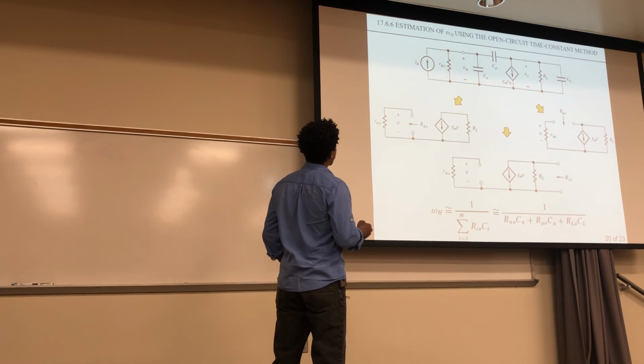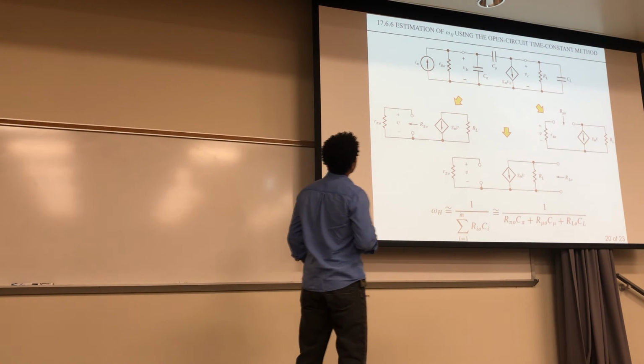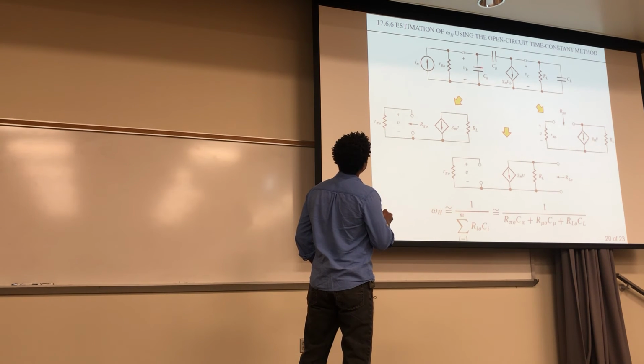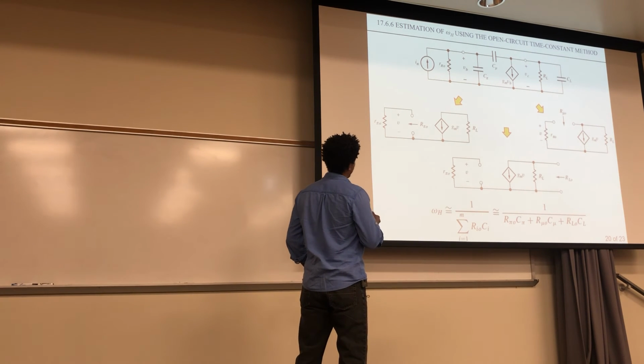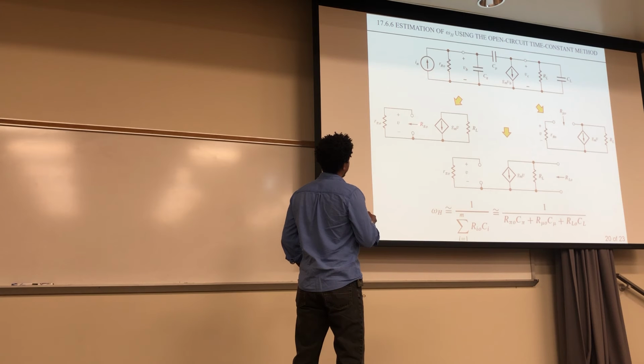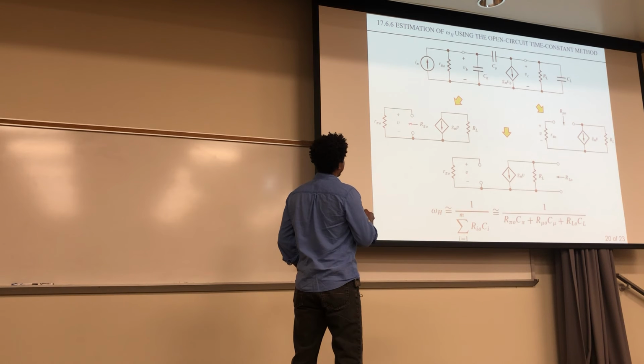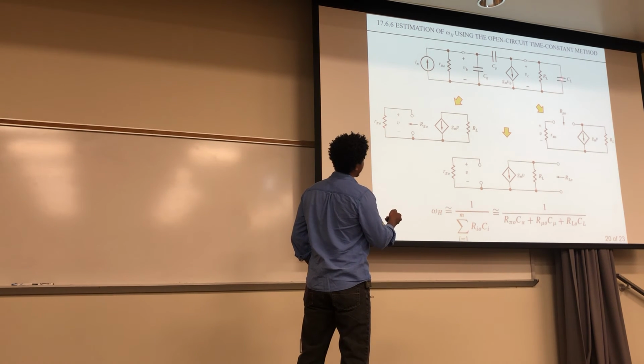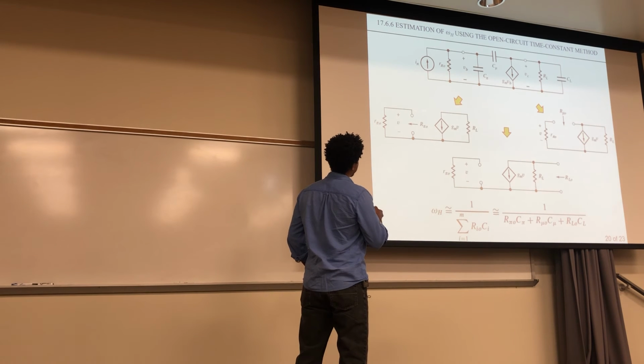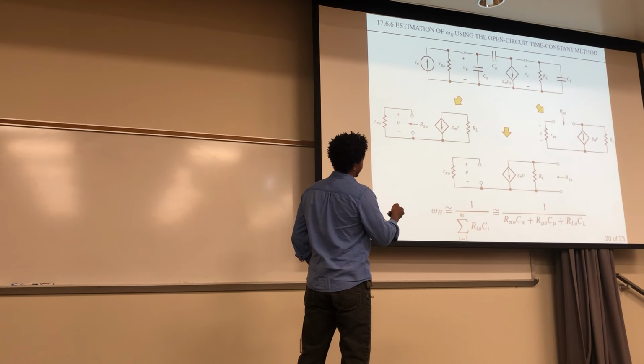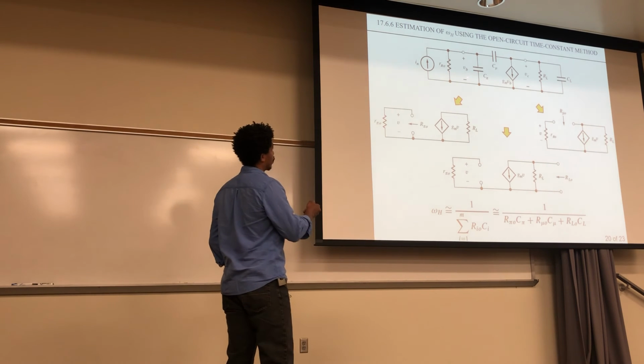So here's our model right here. Okay. Now for this first one right here, C pi, we'll find that and replace it. So we'll find the R from that, right? So we do this by removing this, looking at the resistance, seeing what is gone, and all the other ones, this one and that one, become open. So that's why you have no connection across here, and this bypass, this capacitor in parallel with that is no longer here. Okay, so that's how to find the first one.